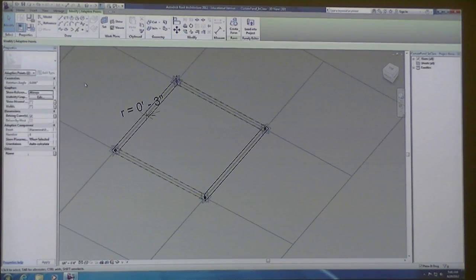If you just draw something free form, not referenced to anything or not hosted to anything on this original setup, you're going to get all kinds of wacky things that would start to happen once you try to apply it to a surface that's being divided. So remember, snapping is very important. If you make a form and you end up applying it to a divided surface and it doesn't look right, it's probably because you haven't snapped to the right adaptive point or the reference plane.